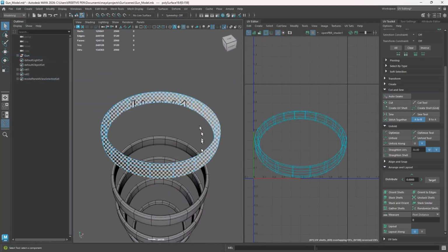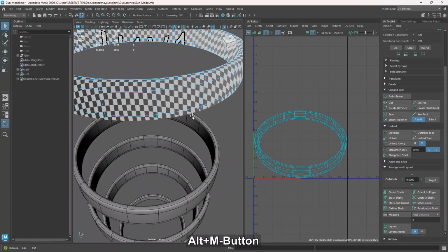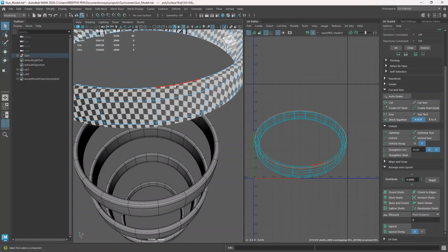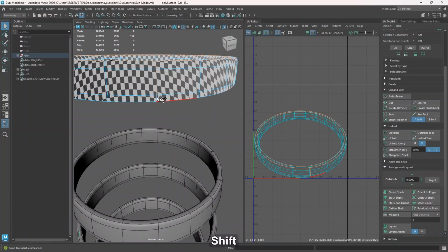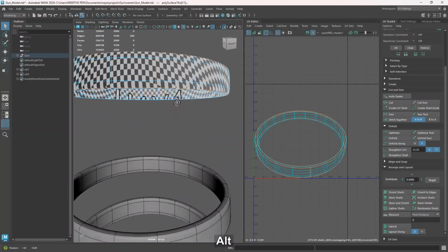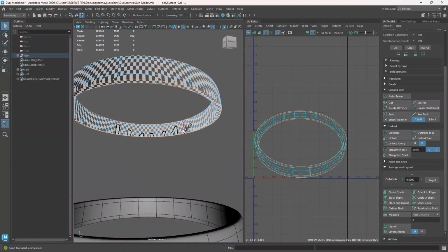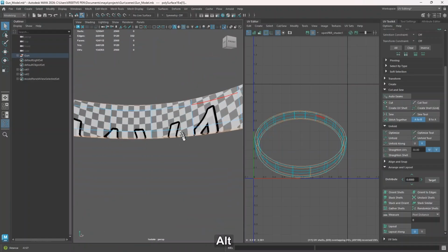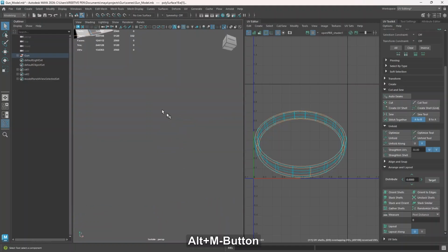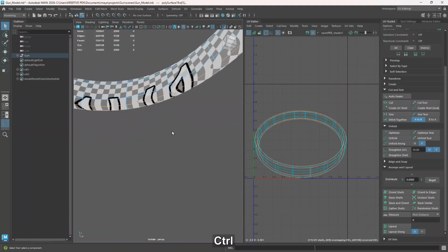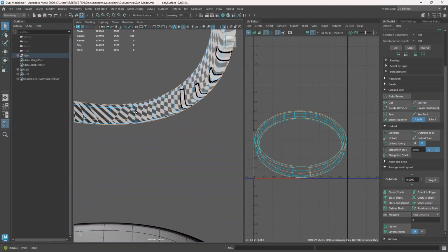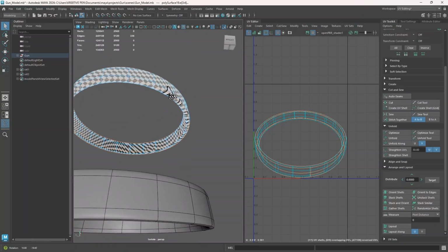And I'm going to right click, go into edge mode, double click to select that edge, hold shift, double click, select this, and also this one, double click to select the edge, double click to select that loop, and finally, by selecting the correct loop.